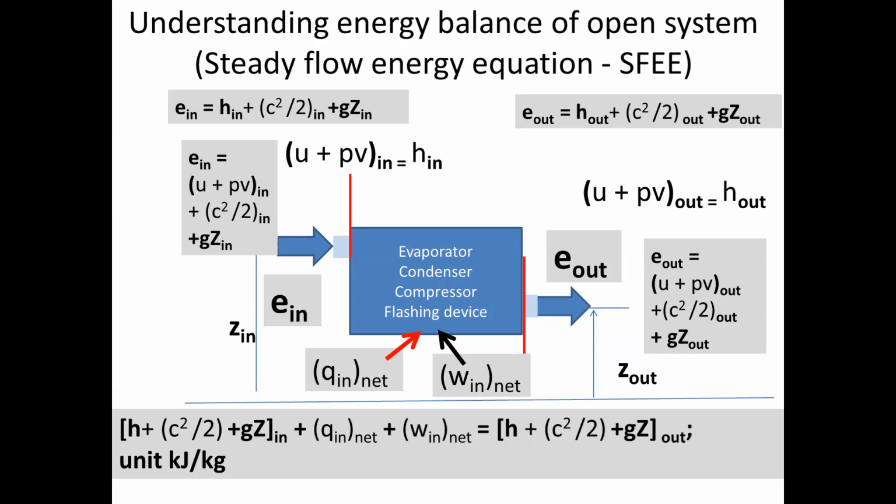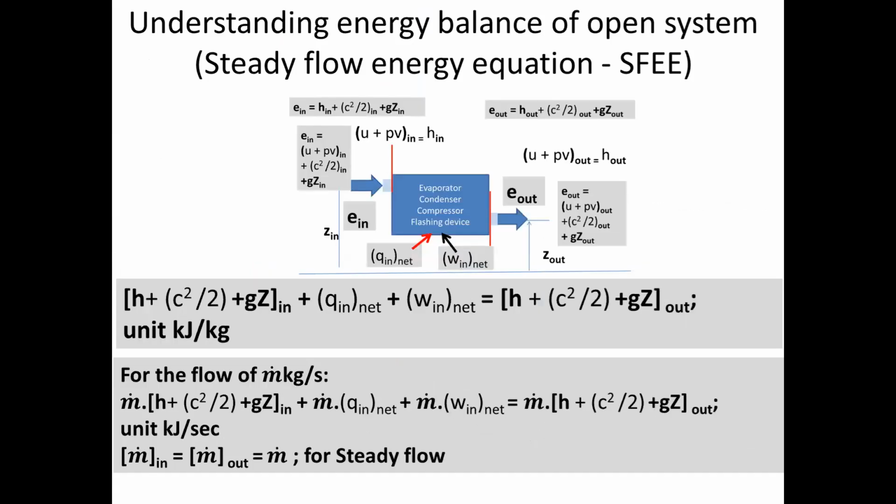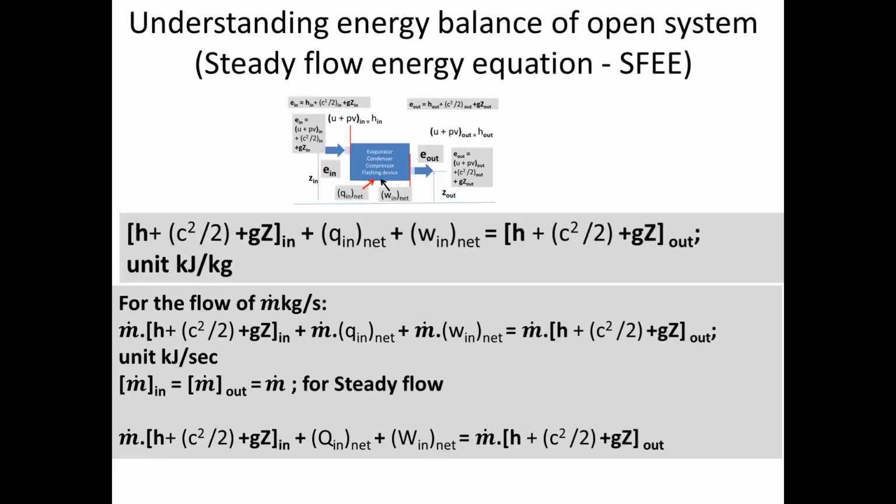Even you should be able to explain this. If I ask you to explain the flow work in steady flow systems, you should be able to explain what flow work means. Okay. If H is U plus PV in steady flows, what PV means, you should know that is the flow work.